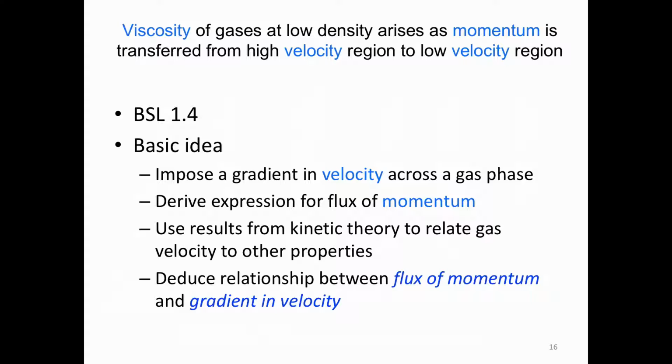And when we applied it, we actually saw that there is something like Newton's law that arises from this derivation. In effect, we had that tau yx is indeed proportional to dvx/dy, and that proportionality constant did not depend on velocity itself. So it was something that depends only on gas properties or molecular properties.